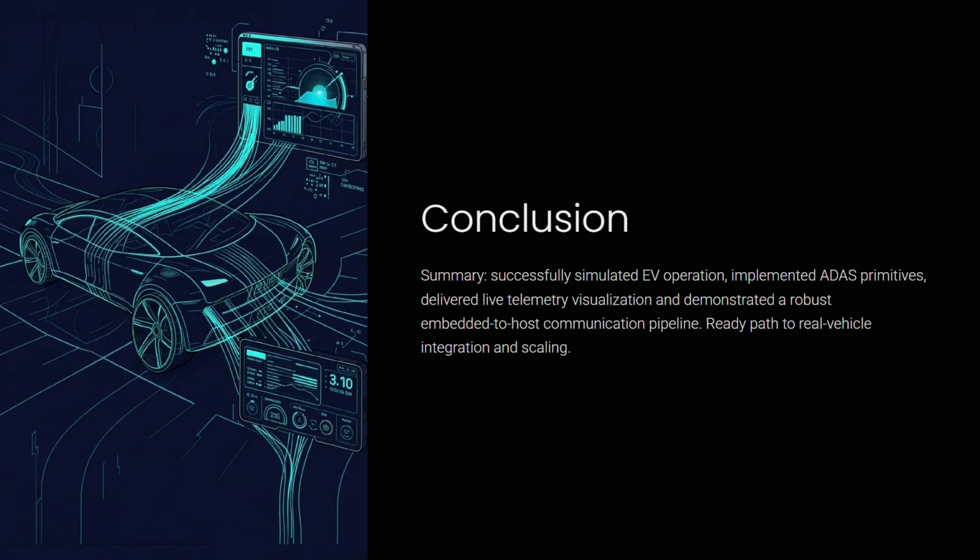Conclusion of the project. In conclusion, this project successfully simulated an electric vehicle dashboard integrated with basic advanced driver assistance system features. The STM32 Blue Pill processes simulated sensor data, provides EV and ADAS calculations, and communicates with a Python dashboard through UART.